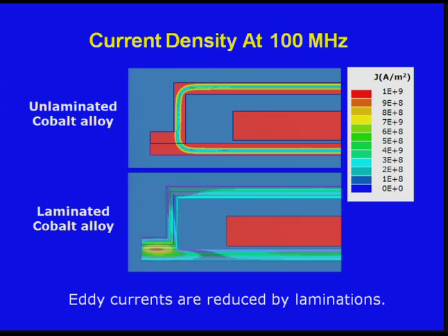We have this magnetic via. And what happens is you get a lot of current flowing in one of the two directions in the magnetic via. So now you have this three-dimensional effect going on. That in itself means that you really have to work on those magnetic vias and make them not allow too much eddy currents. And even when you laminate, you can see that you still end up having eddy currents in those magnetic vias.